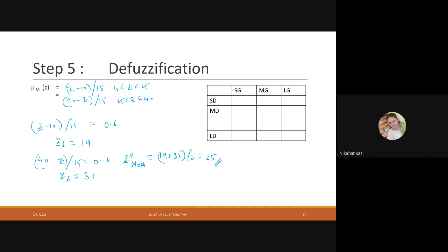You can take higher values of dirt and grease like 80 and 90%, and you will see that the wash time will increase. Of course, it has to increase. So this is how defuzzification is done. Given a value, how to decide the time in which the clothes will be washed, how to set the timer. If you use fuzzy control, the timer will be set automatically. That is how the time is decided.